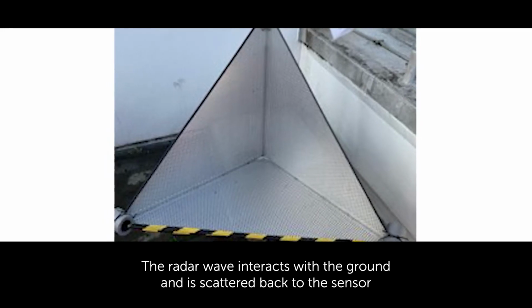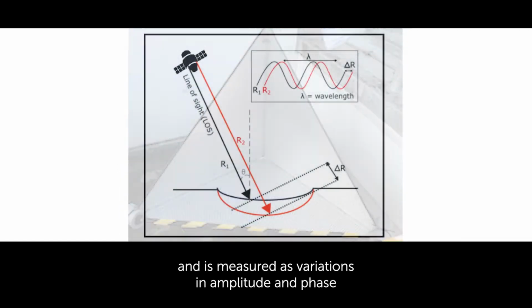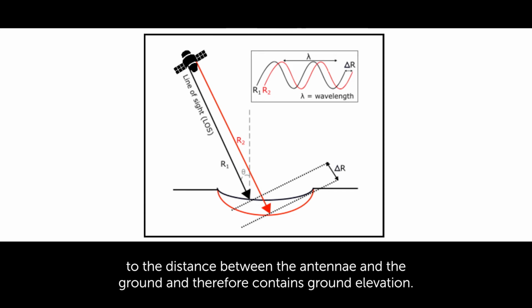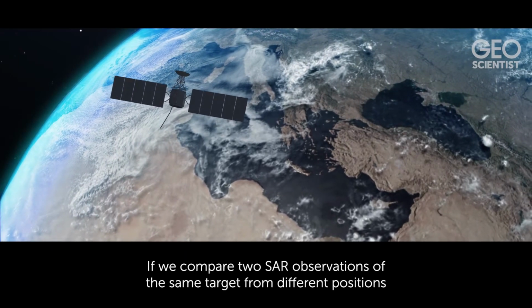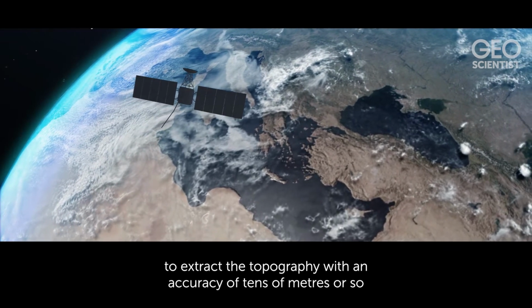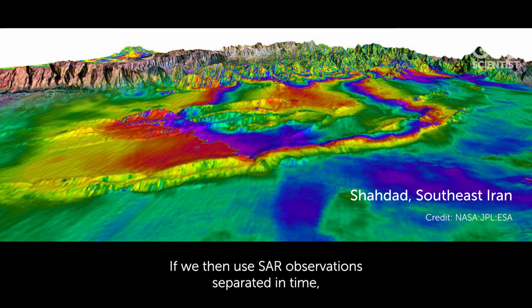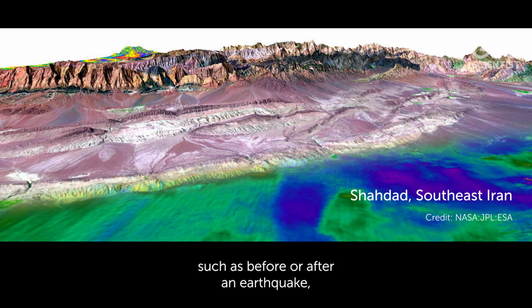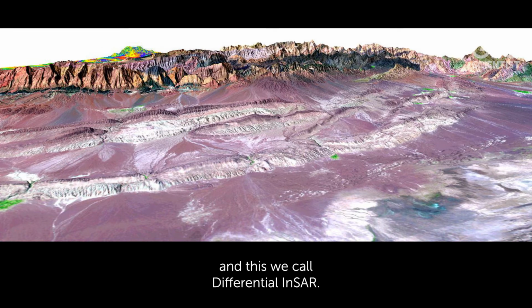The radar wave interacts with the ground and is scattered back to the sensor and measured as variations in amplitude and phase. And the measured fraction of phase is proportional to the distance between the antenna and the ground and therefore contains ground elevation. If we compare two SAR observations of the same target from different positions, we can derive the interferometric phase between them to extract the topography with an accuracy of tens of metres or so, and this is InSAR. If we then use SAR observations separated in time, such as before or after an earthquake, we can extract the differential phase to measure ground displacement at centimetre accuracies, and this we call differential InSAR.